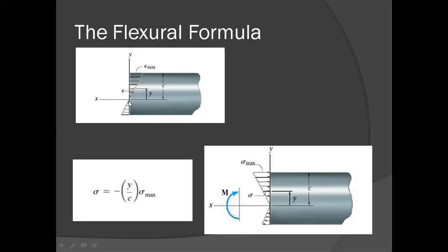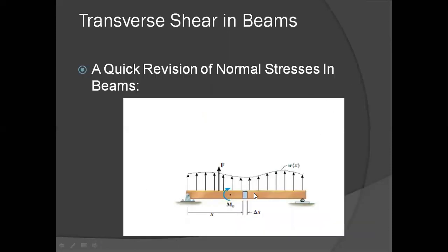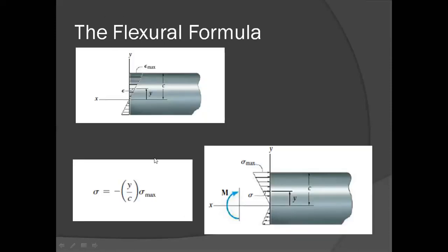The neutral axis is the projection of the neutral plane, the plane which neither undergoes expansion nor compression. It's neither in tension nor in compression, because we know that as the beam is subjected to the load, the upper portion of the beam is under compression and the lower portion of the beam is in tension. So the lower portion is the portion which usually expands, and the upper portion is the portion which undergoes compression.